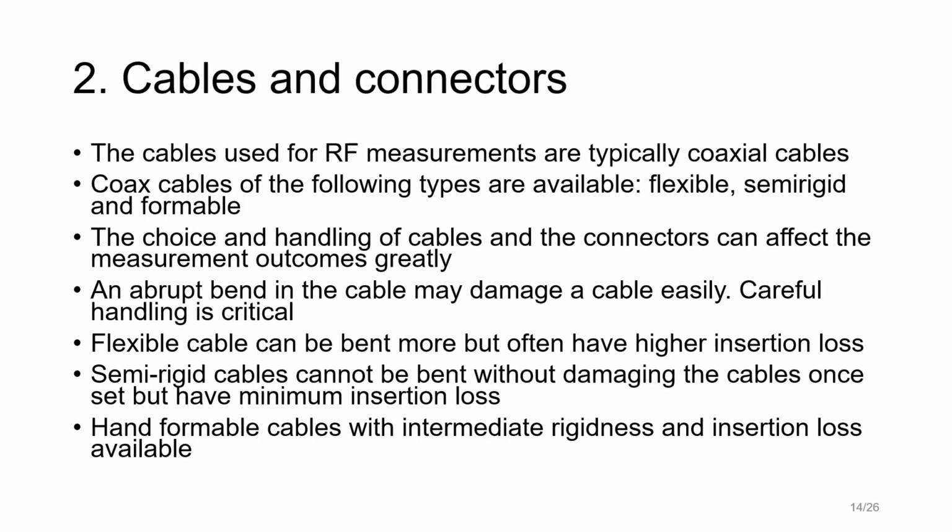So we should not bend it beyond a certain range, and we should not manhandle it at any cost. Even though they are flexible, they have a certain lifetime, and they should not be manhandled, exposed to heat or water. Since flexible cables have braided copper or silver typically as the shield, bending it too much may cause the shielding to loosen.